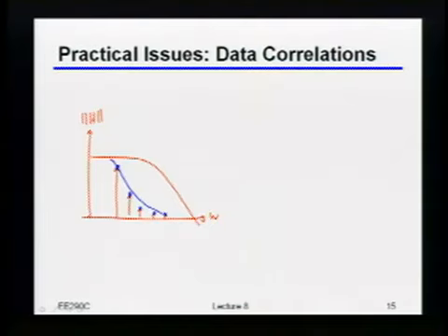You can imagine I'm sending idle sequences for a long period of time, and I could be sending the same idle sequence for a long period of time. So now, if I continue adapting my equalizer on that idle sequence, I'm going to have completely bogus equalization settings. Okay? The good news is it's fairly straightforward to at least not update when you know that potentially you'll be getting bogus directions for the update. So anybody have an idea of how you do that? What's a way of knowing that the data you're getting is bad?